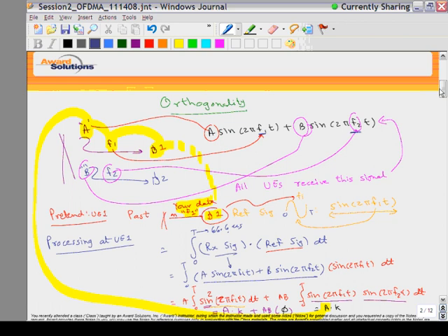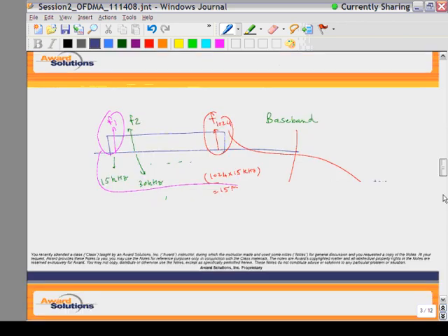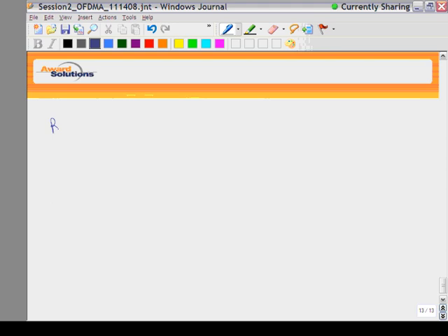To be clear, and then one final question. The symbol rate is always the same even though subcarriers. Correct. Symbol rate always fixed. So very good comment. So let me again draw the picture. Okay, always remember this rule. And what is the rule? One subcarrier carries exactly one modulation symbol, no more, no less, during our modulation symbol period. Always remember that. And there are different terms. The modulation symbol period, also called useful symbol time, and that would be the same as OFDM symbol time.